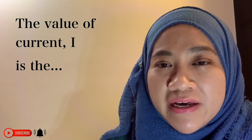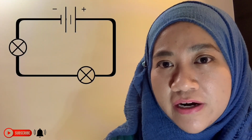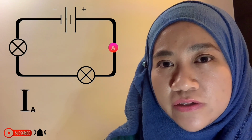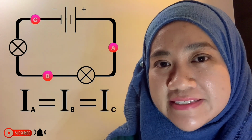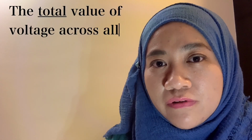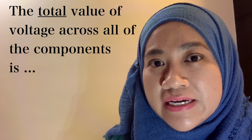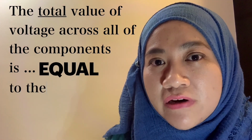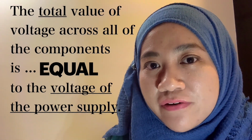In a series circuit, the value of current at any point along the path of the circuit is the same. For example, the value of current at point A is equal to the value of current at point B and also equal to the value of current at point C. However, for the voltage, the total value of voltage across each component along the path of the circuit is equal to the amount of voltage supplied by the dry cell or the battery for the circuit.